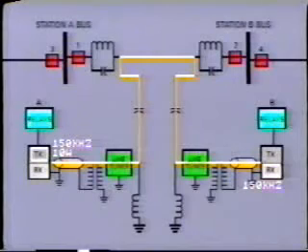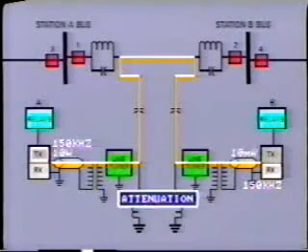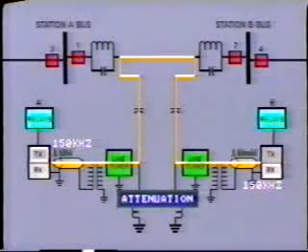As it passes through all this circuitry, the signal strength gets weaker, until at the receiver it may only be, say, 10 milliwatts. This loss of signal strength is known as attenuation. This signal has lost 9.99 watts of power en route. But I can hear you saying we always see signal loss referred to in terms of decibels. Even some of our instruments indicate in units of dB or dBm. What does this all mean?